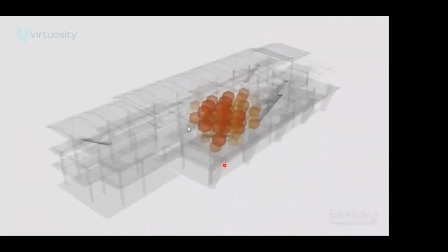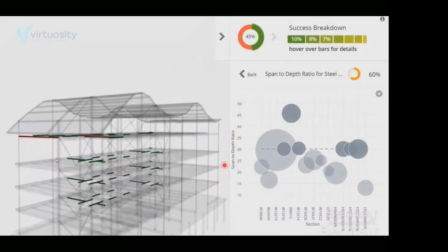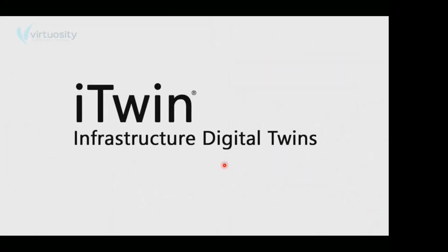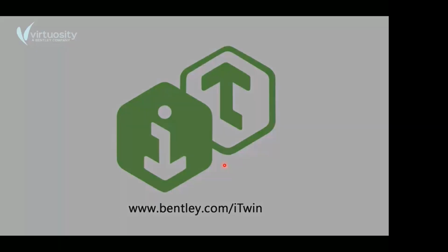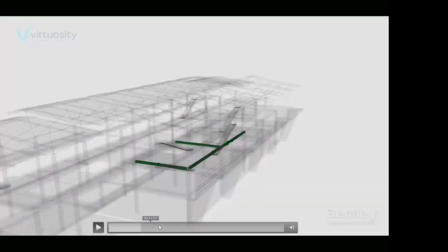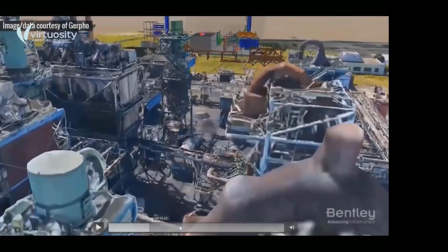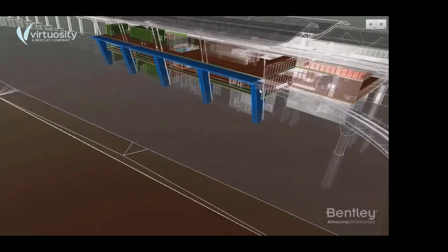So digital twin is a general representation of everything. What is the main difference between digital twin and BIM? Remember that BIM is so important in our infrastructure projects now, but what is the main difference between a BIM model and a digital twin? It is the information data. BIM is just properties and geometry.